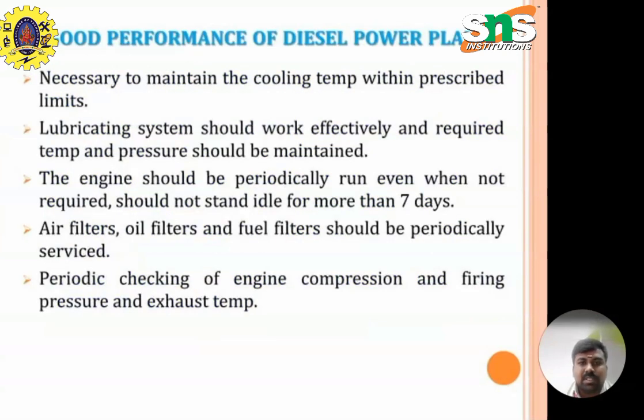For the good performance of diesel power plants, these are the necessary steps to be taken. It is necessary to maintain the cooling temperature within the prescribed limits. The lubricating system should work effectively, and the required temperature and pressure should be maintained. The engine should be run periodically even when not required, and should not stand idle for more than 7 days. Air filters, oil filters and fuel filters should be periodically serviced. Engine compression, firing pressures and exhaust temperature should be checked periodically.